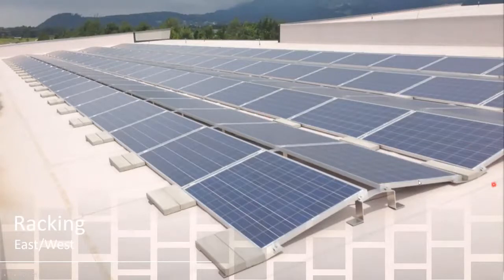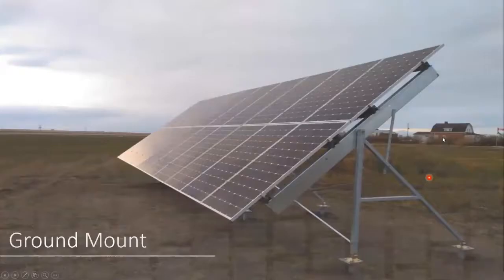So the east-west allows for higher density. As you can see, I have no spacing between the rows. And also it eliminates that wind catch. The downside to east-west facing is production. South facing at the right tilt is always going to be my highest production. Plus side to this from a production standpoint is my east panels never produce maximum power when my west panels are, so I can actually use smaller inverters because I don't have the same issue with pure south facing.